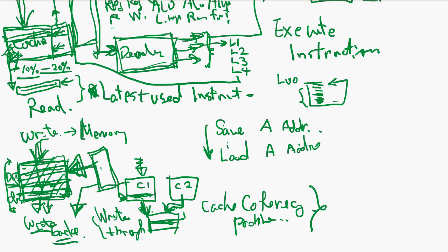We have to do this because we can't have the entire memory on a single chip yet. I mean, we're getting close, but still not, because memory size keeps increasing, and there's no way you can put the entire memory chip onto the CPU chip. If you could do that, then the access time to memory would become much less, maybe 3-4 clocks. Then you could get rid of the cache, right? And we wouldn't have to design such a complicated CPU chip with a cache. But